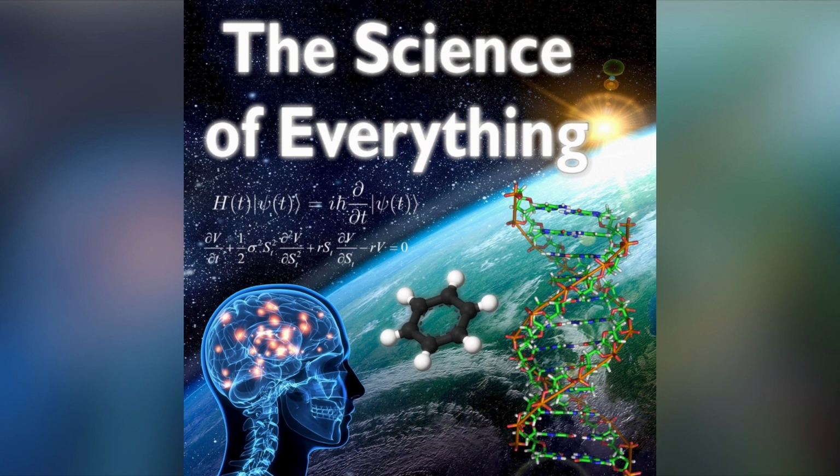Joule heating just refers to the fact that when a current flows through something, it heats it up. That's precisely the same principle that allows electric light globes to work. The Joule heating heats up the tungsten filament, which then glows. So if there's a current flowing across your arm, then your arm is going to heat up through Joule heating, and then your arm gets hot and your skin gets burnt, and that's bad. So that's one source of harm from electricity.